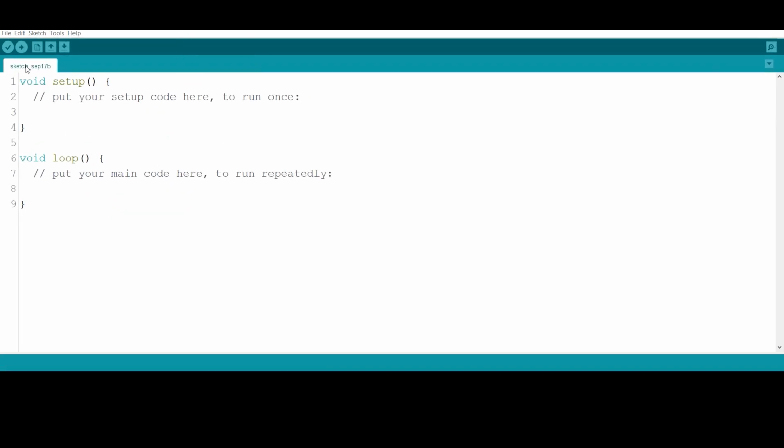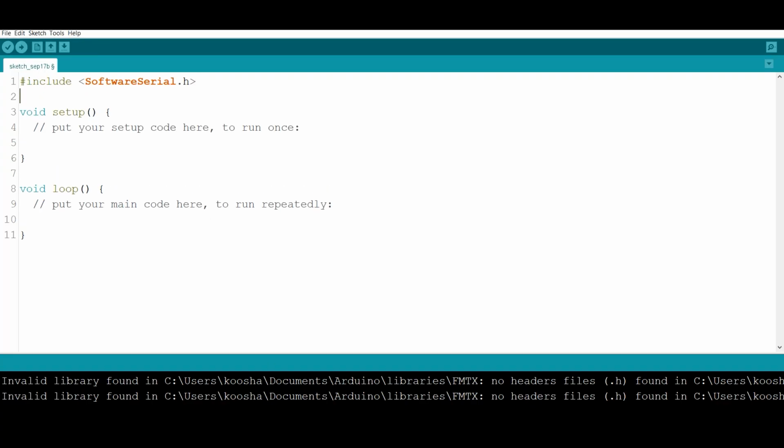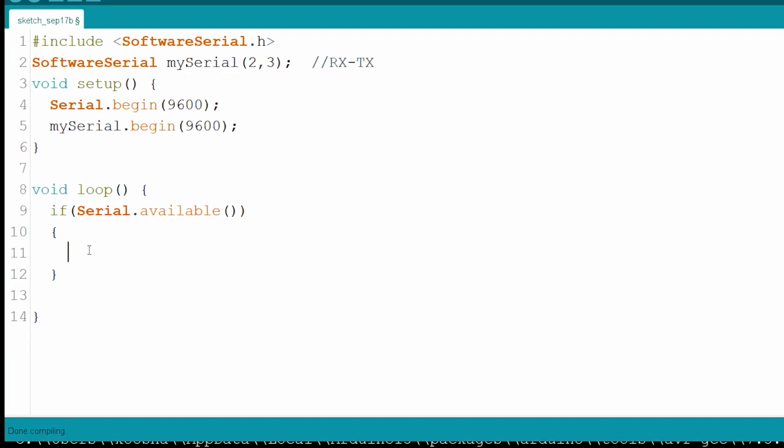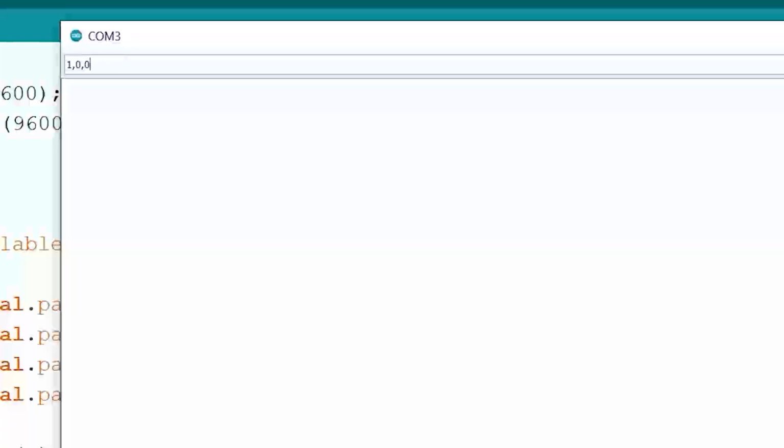On the Arduino side, I'm using the SoftwareSerial library to send data. With the command I wrote, pin 3 acts as the transmitter, which is connected to the input of the voltage divider in the circuit. I will also share with you the complete circuit diagram. In the Arduino code, I've written commands that receive the data from the physical serial interface and then send it to the STM32 in the same format. I tested several times and it worked perfectly.